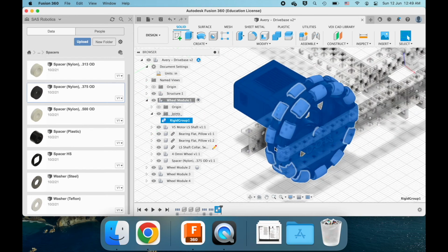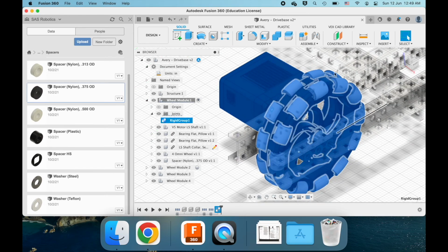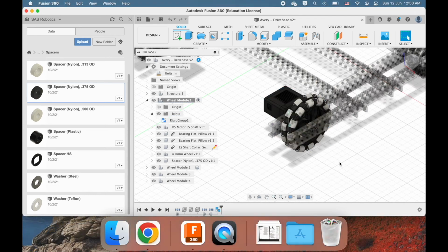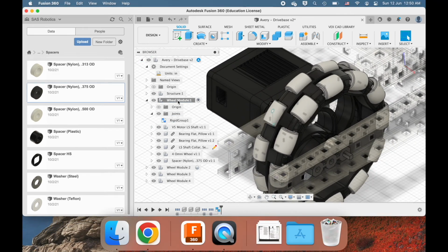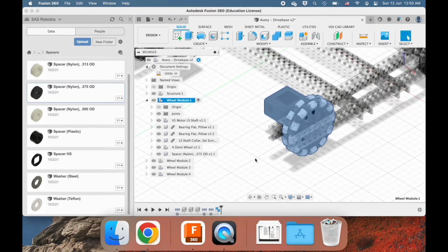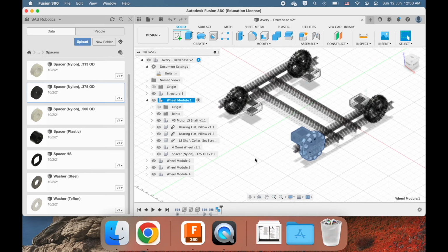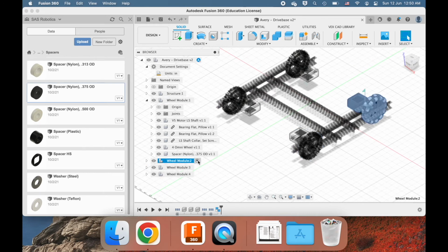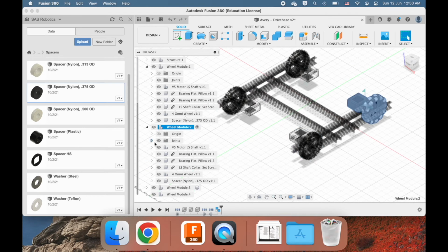And what does a rigid group do? It makes sure all the pieces within the group are positioned exactly the same relative to each other. And because we applied this change to one of the components, this is similar to how the modify tool worked on the C channels in the previous video, right? Now go to another file, and that same rigid group is going to be in it.